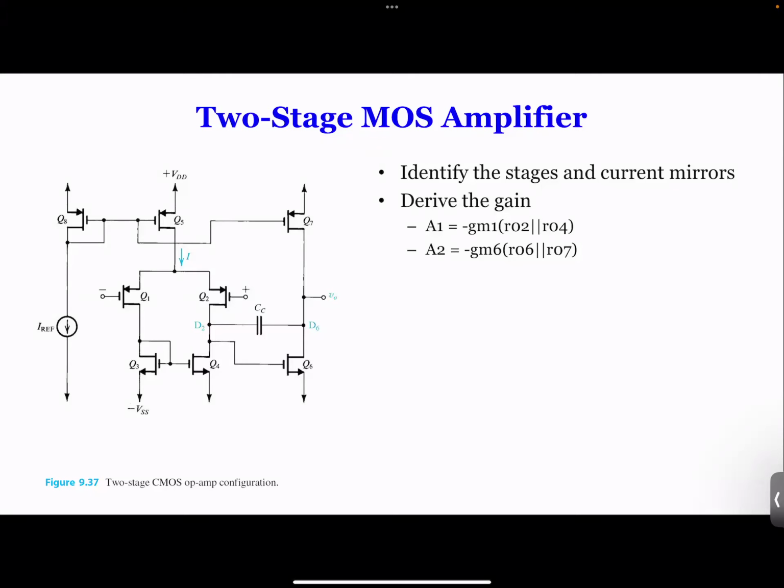For the small signal amplifier, what we mean is that we always have a small AC input that is added on top of the DC, and then at the output, if you don't have a capacitor at the output, like next chapter we're going to look at the differential frequency response, if you use a scope, many of these amplifiers, you will see AC added on top of the DC output.